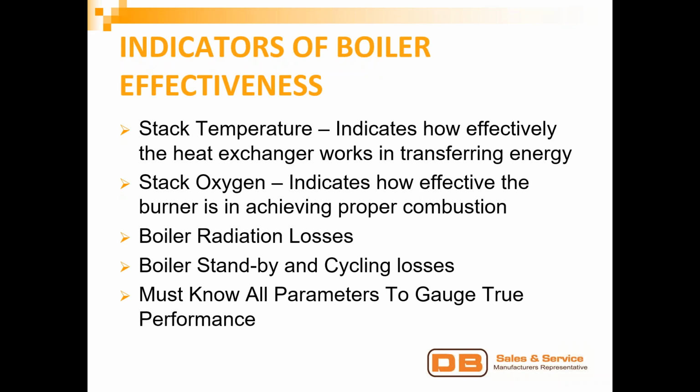Some indicators of boiler effectiveness. A boiler in its root element is really a heat exchanger. It's exchanging heat from combusted gas into water or steam on the other side of that heat exchanger. Stack temperature is a great indicator of how effective that heat exchanger is working in transferring energy from the combusted gases into the water or steam on the other side of the boiler.